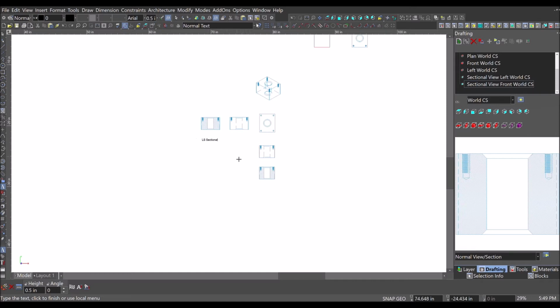That is called the command center. So when I select a tool and I have to give it some parameters, or I need to change the parameters, you'll see me do it down there. If you look at the lower right-hand corner, you're going to see the X, Y, Z. Those are the geo coordinates. That is what is sent to your CNC machine.